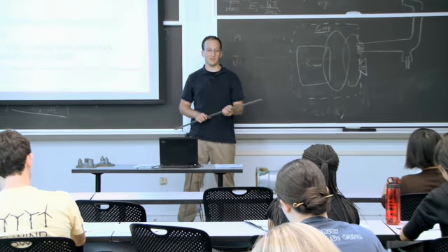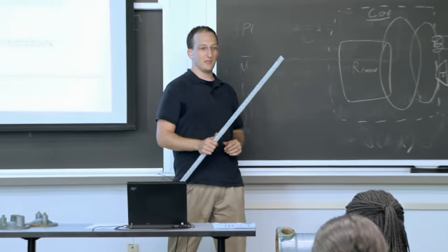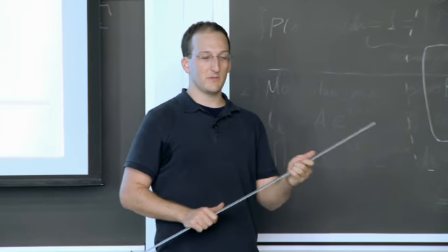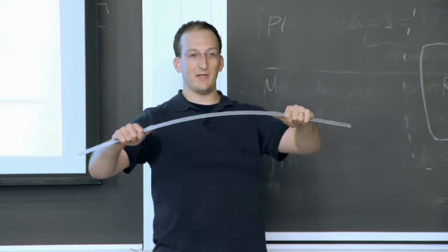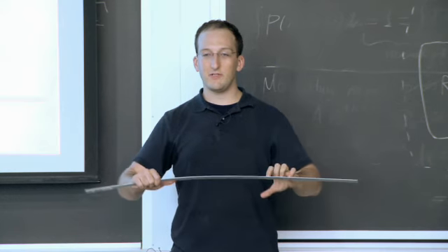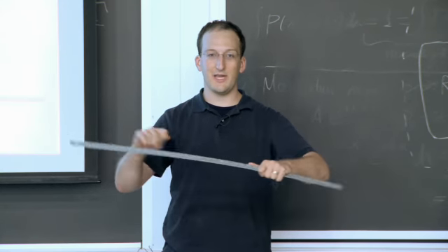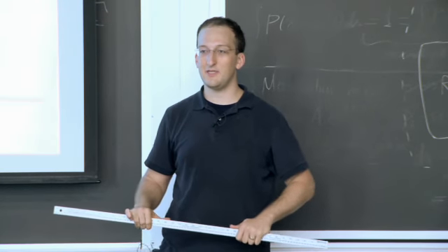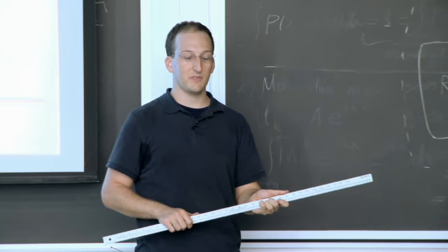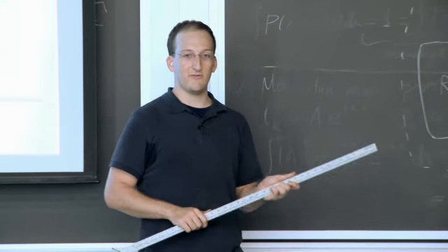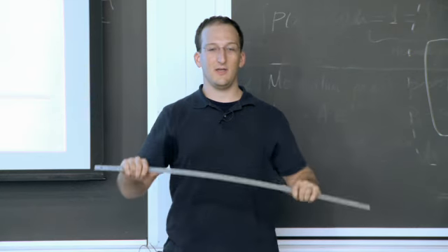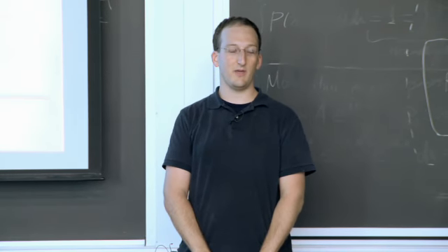I will be doing materials a little later, but I can just tell you now, if you have a piece of steel, which at room temperature is normally ferrite or pearlite or martensite, some sort of harder phase. If you bend it and it doesn't bend back, you've plastically deformed it, and you can do what's called work hardening. Have any of you guys ever taken a piece of copper wire and bent it a couple times and it just snaps apart? The same sort of thing happens in steel, except you have to bend it more. If you heat it up to the point where it transforms from a body-centered cubic crystal structure to face-centered cubic, from ferrite to austenite, you can just sort of deform it like this. It's got more slip systems, more ways to deform, and it's hotter.